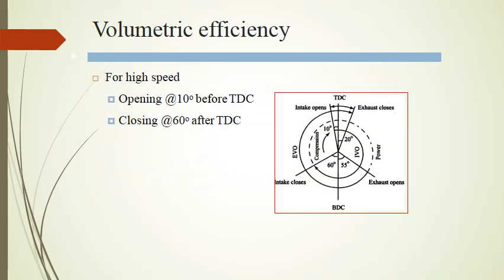Now this is the valve timing diagram for a high speed engine. Here the opening of the intake valve takes place 10 degrees before top dead center, but the intake valve closes 60 degrees after top dead center.